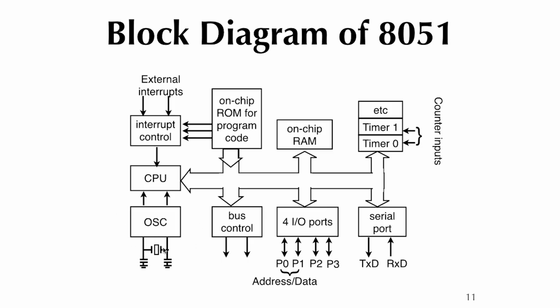Oscillator, what does it do? The oscillator is kind of a heartbeat generator, right? All digital systems have some crystal to generate a clock frequency. You might have a 1.5 gigahertz Pentium, but here, no, this is a couple of megahertz. Much slower, but much lower power. A crystal is quartz or something, where if you apply some voltage, it oscillates and generates very precise pulses. You have crystal-oscillator-driven watches, very precise, like quartz ones. Some of these may be silicon ones, less precise, but still workable.